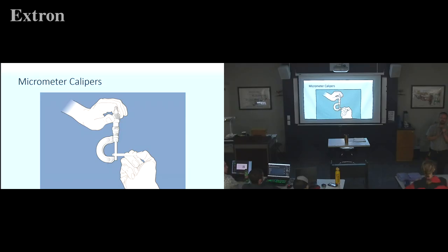Micrometer. So this is a precision tool. Vernier caliper is not a precision tool. Okay. And that is actually a written question. Which one is the most precise? I can't remember what the written question is. You guys are supposed to be studying prepware. I can't think of the word, but it's like, which one is a precision tool for measuring engine parts? And it would be the micrometer. Okay? So this is going to be the most precise.